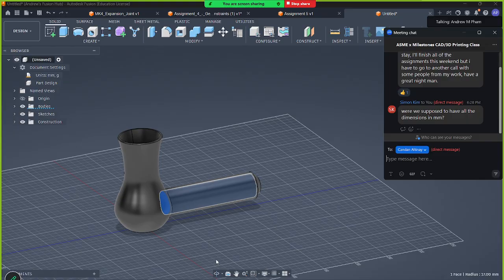One of the things I find myself doing often is like with all the chamfers and fillets, I typically add them at the end because they're usually not super critical to the geometry, and they're just kind of there to make things look a little bit better. But when you have them in the middle of your timeline and you want to move things around, sometimes it can kind of create dependencies, right?